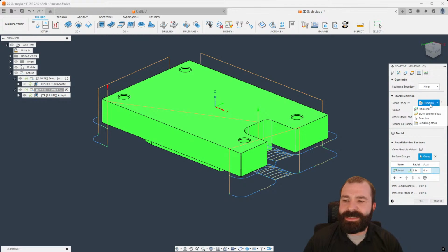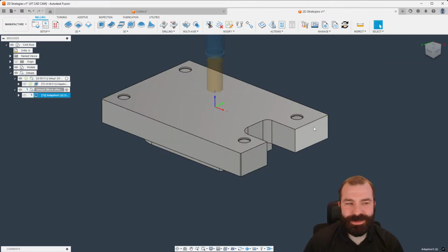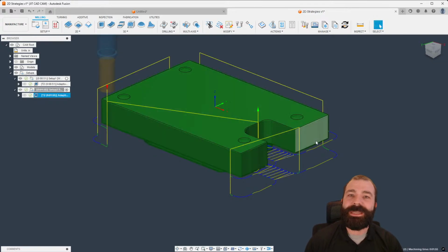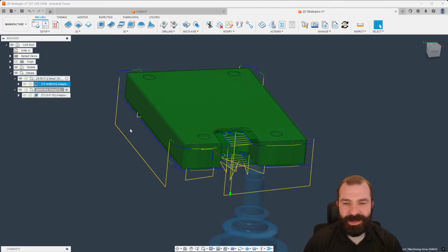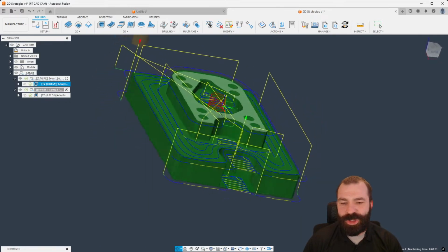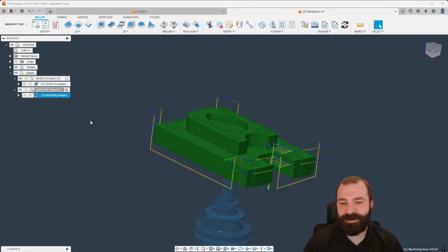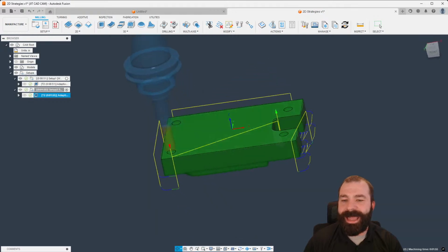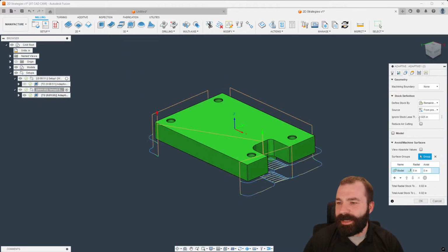So this is something that, based on how you program in Fusion, we've always wondered: is there a way to get it to avoid those areas? But with 3D adaptive clearing, Autodesk, if you guys are watching, there is still the issue where it's trying to go in somewhere that we've already machined the other way. Presumably we should expect it to do a little bit down here at the bottom, but that's not the case when we flip this over, because we're creating a lot of ghost paths that aren't necessarily needed. So again, let's go back in, see what we got.